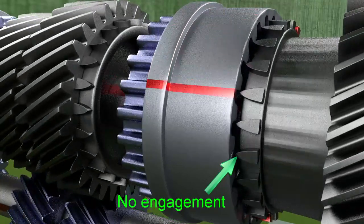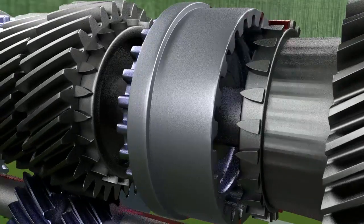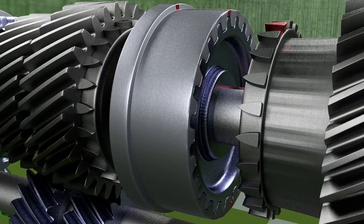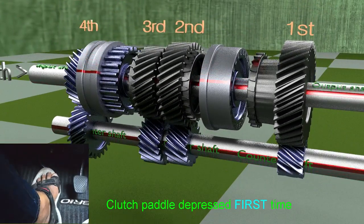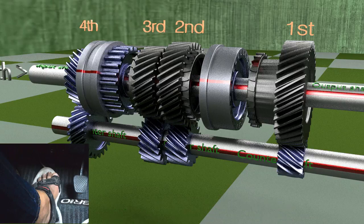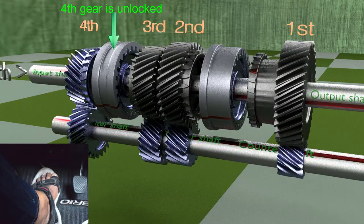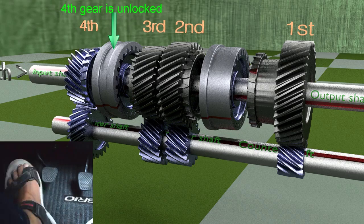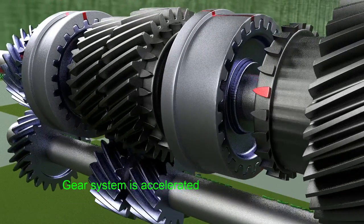To engage the shift sleeve with the first gear, the speed of the first gear has to be increased to match the speed of the shift sleeve. To do so, the clutch is disengaged first time by depressing the clutch pedal and the gear system is brought to neutral position. Then the clutch is engaged by releasing the clutch pedal and the engine is accelerated to increase the speed of the gear system.